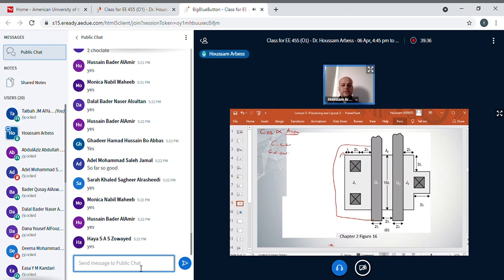Here we have the P plus field implant, and this capacitance in general is proportional to the perimeter of this P plus field implant. So now you have to know how to calculate the area of the junction and the perimeter of the junction.